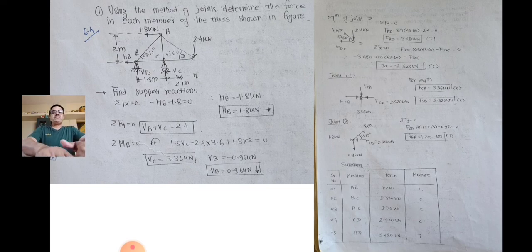Now here, since the forces in members AC and BC are the two unknowns, one can assume tensile directions for these two unknowns, or using your logic you can select correct directions for them. If you consider tensile direction for FAC and FCB, in that case your answers may have a negative sign. So you can use your logic to assume suitable directions for these unknowns.